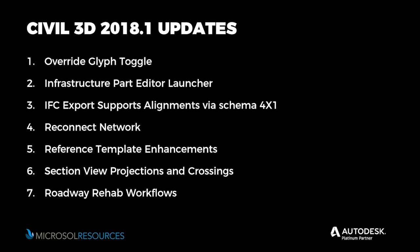With 2018.1, Civil 3D gained the ability to export alignment data directly to IFC. There was one item, item number 4, the ability to reconnect networks. There was an issue. I never saw it in the wild, and I never had any clients reach out, but it was a known issue that certain clients experienced and certain end users experienced, where if you upgraded Civil 3D drawings with pipe networks, all your structures and pipes got disconnected, right? Which is a nightmare, because if you don't have an easy way to reconnect a large network, you'd have to do a lot of that work manually. So that tool is introduced.